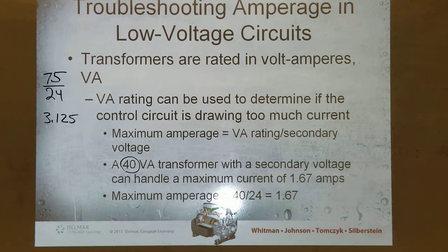So if you're drawing more than that, guess what? You've got a problem somewhere. That's also how you size your fuse. So you put a 3 amp fuse in there and go for it.